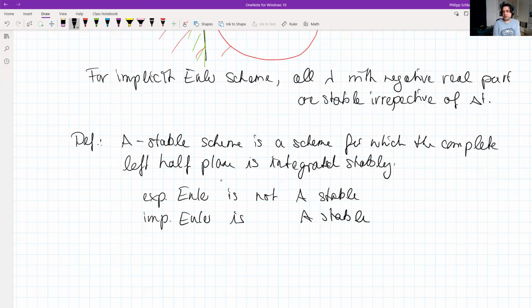That, of course, also means that even though you could use larger time steps for the implicit Euler, so you can have very, very large time steps to do the time integration, the problem is the leading error term is still proportional to delta t. So the larger your time step is, the larger your error, of course, becomes. So that means it's not a solution to always take implicit methods and then time integrate with huge time steps. That will not give you an accurate solution because you still have a very large error in time. The solution will not blow up. Okay, fair enough, but it will not be accurate.